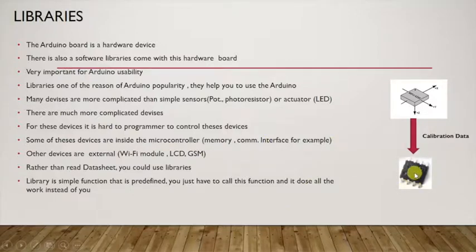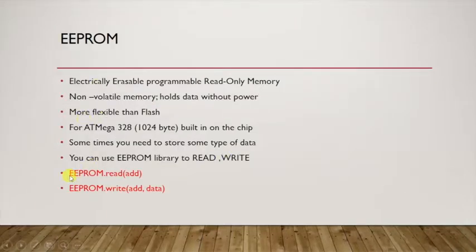The EEPROM is inside your Arduino, inside the AVR microcontroller. It's not easy to program this EEPROM, but I don't have to worry about how to save the data on it. I simply use two functions: EEPROM.write to save the data to a specific address, and when I want to use the device, only the EEPROM.read function is called, and I can use the calibration data. So with the EEPROM library, I don't worry about the hardware.